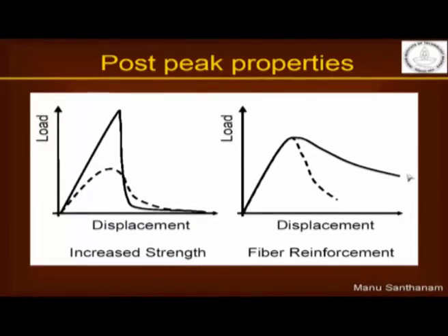They prevent the wound from opening up so that there is some healing that takes place. Similarly, fibers that are bridging the cracks ensure that the cracks do not open up very fast and have a very gradual opening to failure. So the fibers prevent the cracks from growing to failure suddenly, and they have a very gradual opening of the cracks towards failure. So fibers help in improving the post peak response of the concrete and make concrete more ductile.